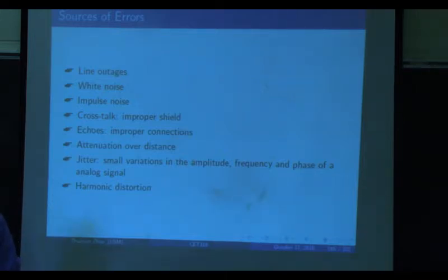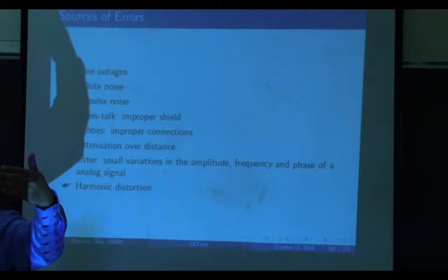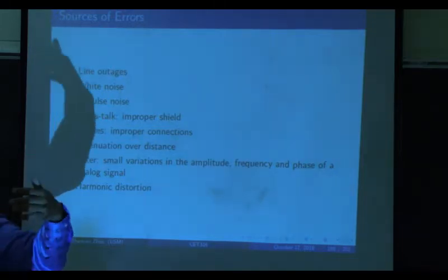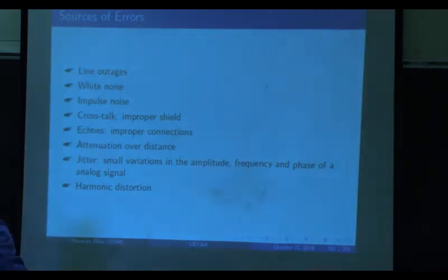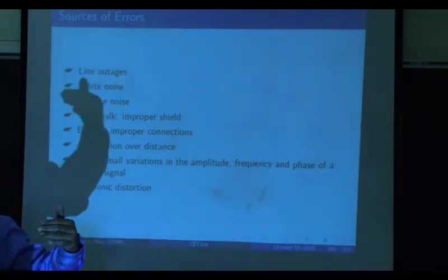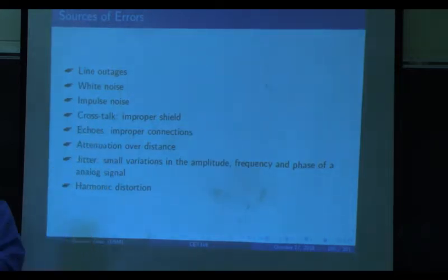Probably a line broke or so, because of the impedance mismatching. For example, when you design amplifiers, you have stage 1, stage 2, stage 3. All these different stages must have the input impedance and the output impedance matched, for complete signal power transfer.